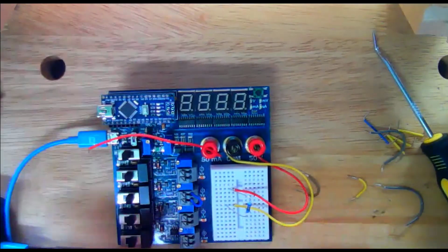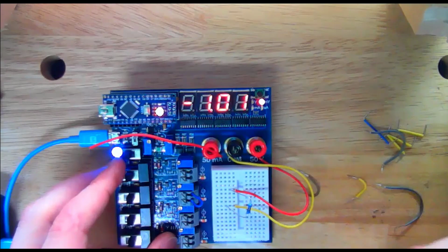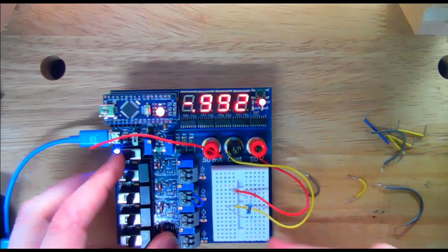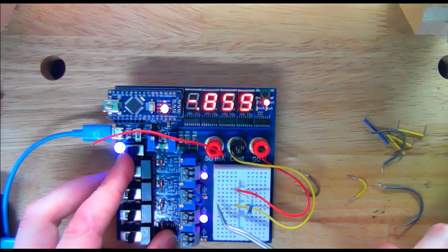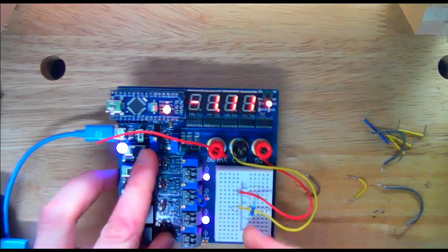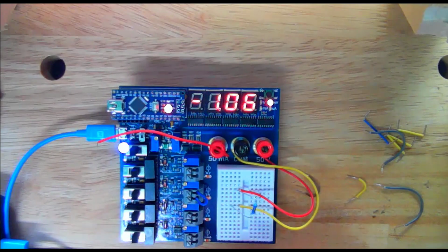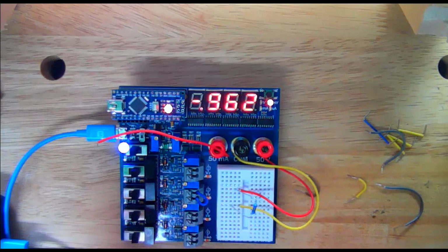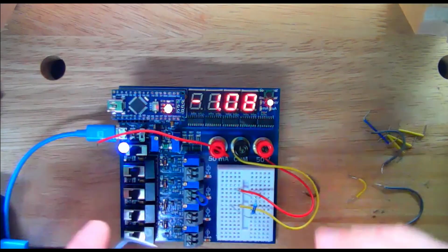Let's see what happens when we fire this thing up now. When I energize this, this supply is shorted. These other ones are not. And you'll notice the light for this one does not turn on. The light for this one is off. And that's one of the ways that the lights serve as an indicator of something's gone wrong. So if you look at the lights and they're really bright or they're off, turn off your circuit immediately. Something's wrong with your circuit. You've got to go back and check.